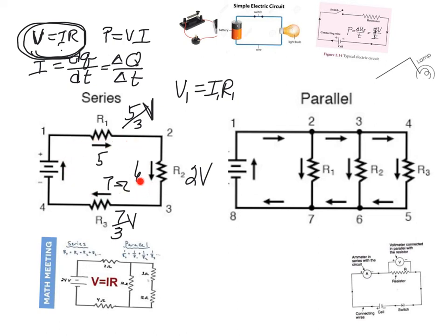And this leads to the idea that we'll talk about later, Kirchhoff's law, which says the sum of the voltages in a closed loop has to be 0. So this would be considered a positive 6. This would be a negative 5/3, a negative 2, and a negative 7/3. And when we added all those, we would get 0.